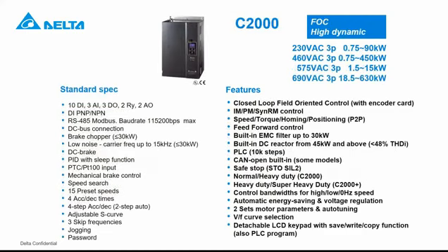Now, moving on to our standard high-performance drive, the C2000, which can run motors in field-oriented control, so that is with encoders. We support a number of different encoders, anywhere from ABZ to sine-cosine, to resolvers, and also encoders with commutation signals and all of that. You can use the drive to run PM motors or synchronous reluctance motors, and of course also induction motors.